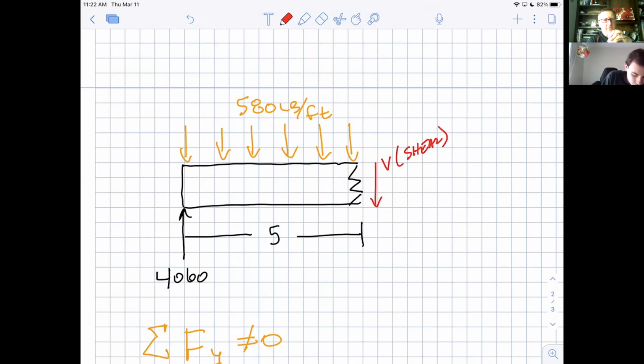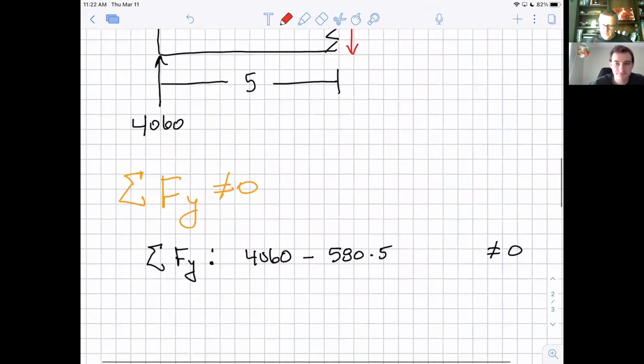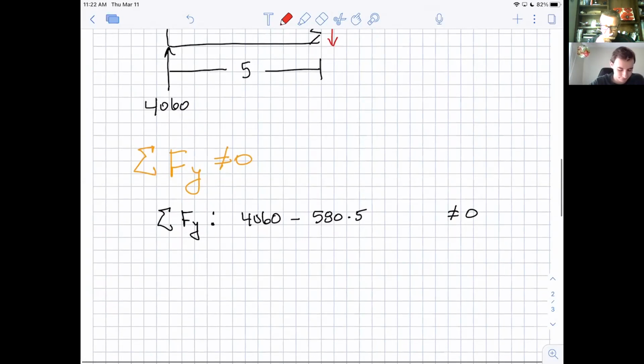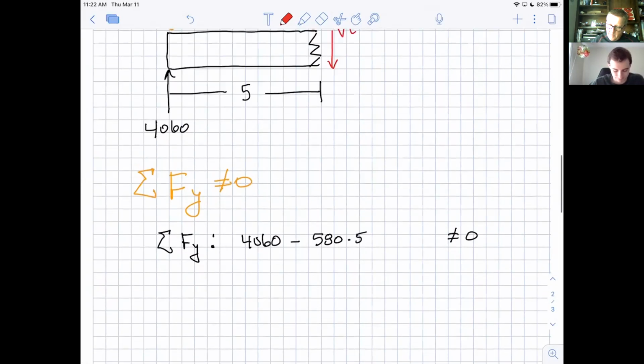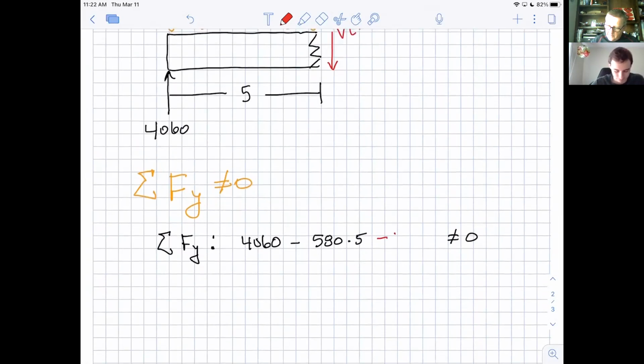And so there's a force missing here, just like for the joints. When we showed that a beam was connected at the corner by a fixed joint, we said, hey, that fixed joint is going to provide some resistance, right? We said that's not going to let it lift up or push left or push right. Well, isn't that beam attached to something? So wouldn't there be some shear force there? Well, that's how we make this equal to 0. And this is so important. So watch this. If I go back here then, and I say minus V, notice V is down, then I actually can get this equal to 0, can't I?